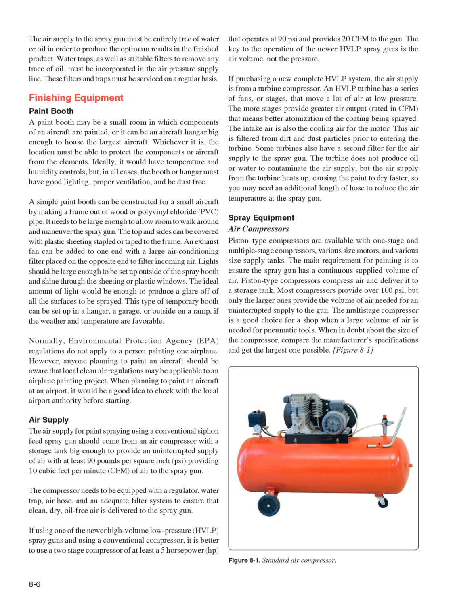An exhaust fan can be added to one end with a large air conditioning filter placed on the opposite end to filter incoming air. Lights should be large enough to be set up outside of the spray booth and shine through the sheeting or plastic windows. The ideal amount of light would be enough to produce a glare off of all the surfaces to be sprayed. This type of temporary booth can be set up in a hangar, a garage, or outside on a ramp, if the weather and temperature are favorable.